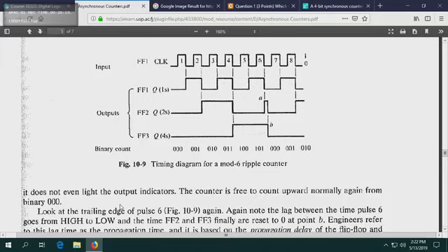All right? So remember that these things here, synchronous counters or asynchronous counters or ripple counters, they count in sequence. Synchronous counters count according to the designer's state diagram, right? We can do random numbers here, but it will be very, very messy. Basically, the only tool you have is to use the preset and the clear. How many times are you going to use that? All right? Okay. Now, let's have a look at the next picture.